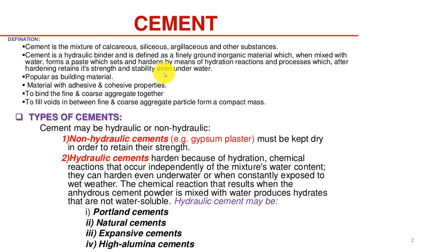In your concrete mix, you can imagine that you have 50 to 60% coarse aggregate, 20 to 30% fine aggregate, and 10 to 15 to 20% binder, and that is conventional concrete. So the spaces between the coarse aggregate are filled by fine aggregate particles or some type of fillers, and there are quite wide spaces among the aggregate particles.